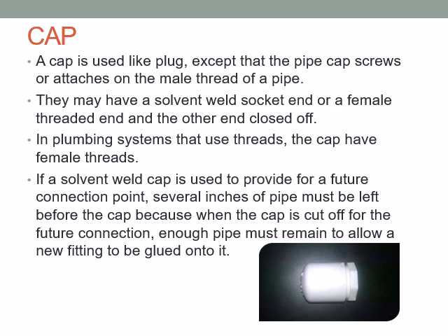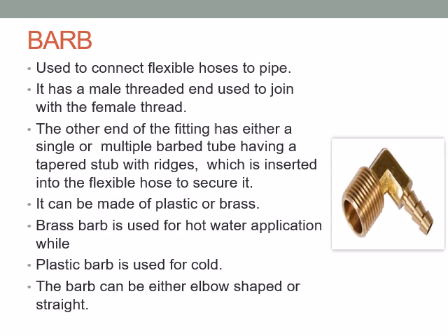If a solvent weld cap is used to provide for a future connection point, several inches of pipe must be left before the cap, because when the cap is cut off for the future connection, enough pipe must remain to allow the new fitting to be glued on it. Mainly the cap will be used to terminate the flow, that is, for closing purposes.